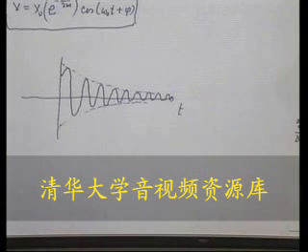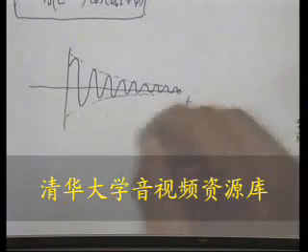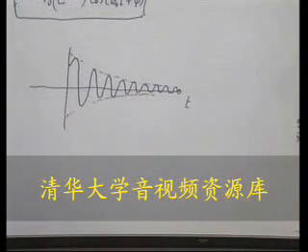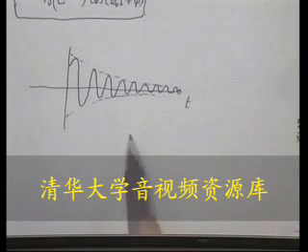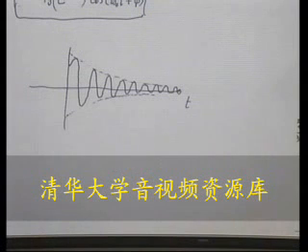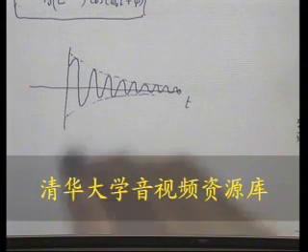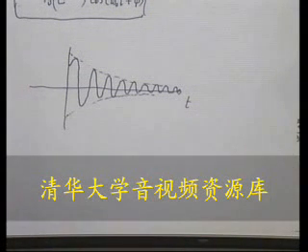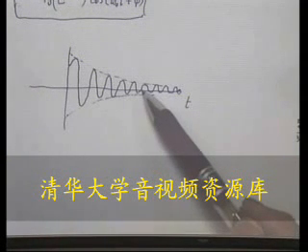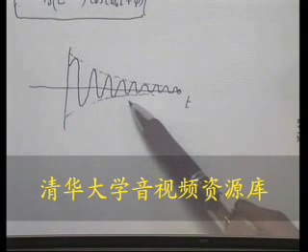All oscillations follow this. If you have a very small damping, then you can go on and on and on. The book has a diagram with a much smaller damping than what I had. How do you count the damping? You count the number of oscillations before it goes down by a factor of 2. And this one damps down maybe after 6 cycles.